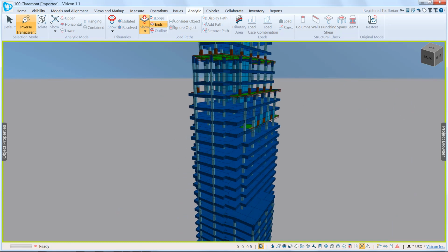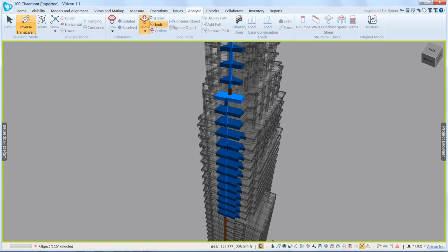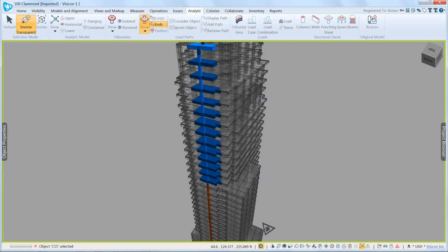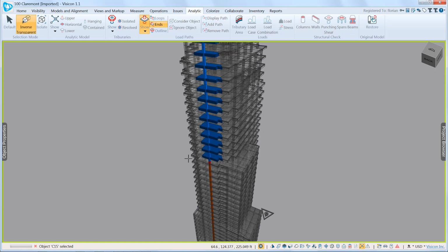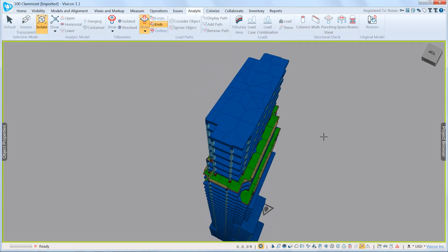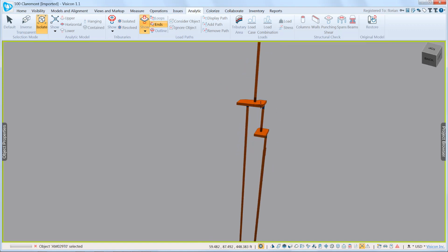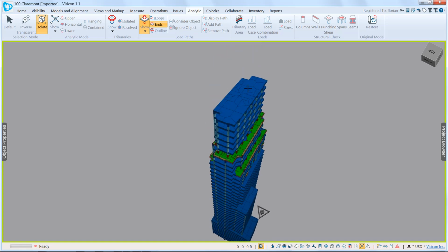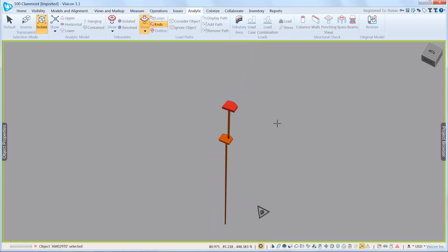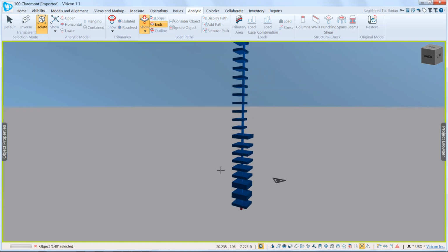While we're in this mode, we can also display the individual load paths. So if I select any support, it highlights the tributaries that are contributing to the load at that point. So here we can see it has the transfer, and from that point downwards it takes the path down. It doesn't include any of the tributaries because here we're just going the other way. I can isolate those. I can grab any point at the top. So here, for example, that roof panel has a column. There's a transfer at this level. This particular column then is continuous all the way to the foundation, and then the secondary column has another transfer in it. So there are two ways that you can display the load path: by selecting from the top, or inversely selecting any of the supports at the bottom and seeing what contributes to the load of the column.